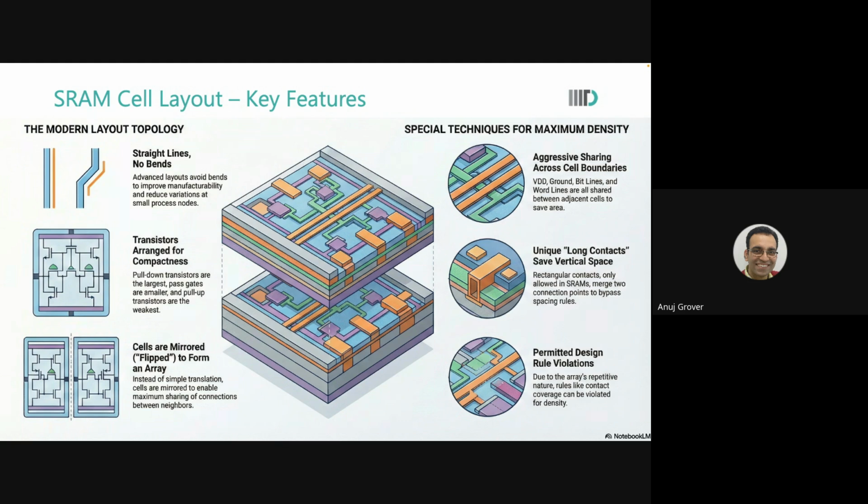You want to reduce the height there. So you see that, okay, if I keep the same metal to metal, I can't get it. If I put everything on the metal to metal, then there is a risk of short happening. So I will take something away from metal to metal. Then I will take something away from contact coverage also. There is also another DRC on minimum area that you can have for a metal stub.